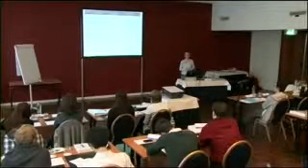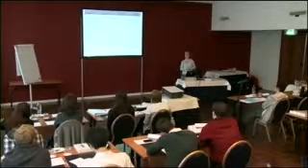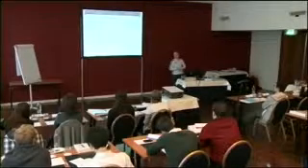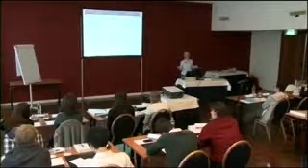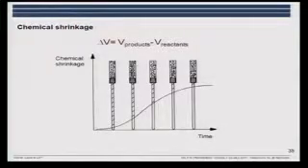So, how much water would I need to have full hydration? 0.42, yeah. If I didn't have extra water coming from the exterior. And chemical shrinkage, you saw it.